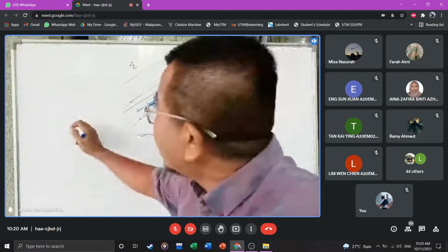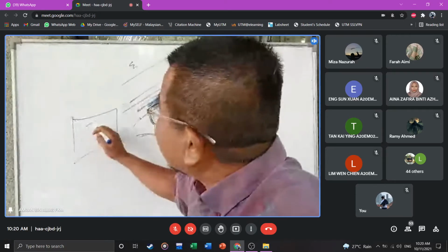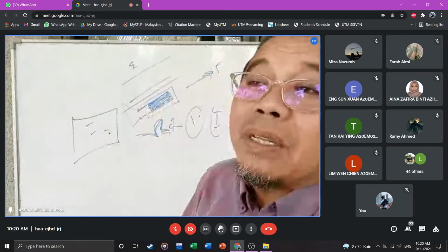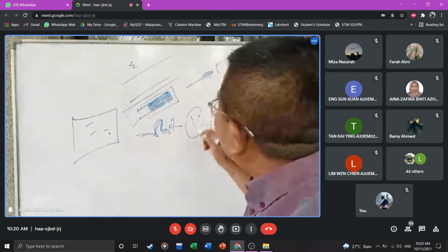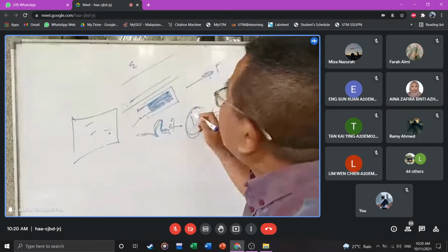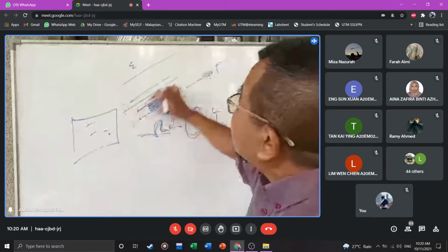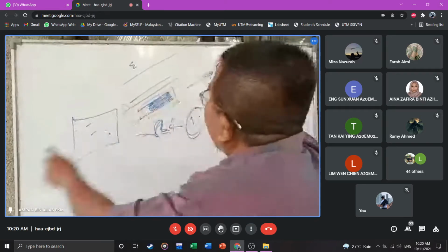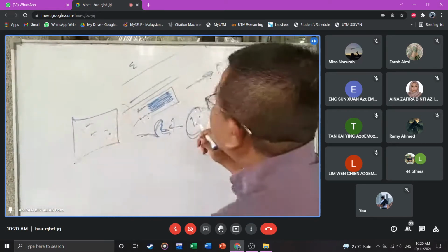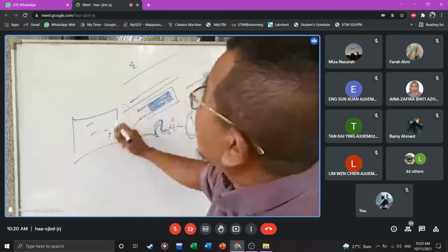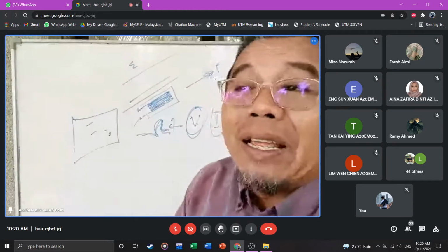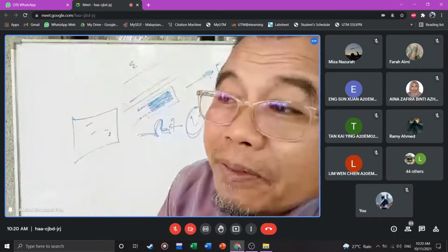That's how the strain gauge meter is working. It's just calibration. If you are reading the voltage, the voltage is changing with the resistance, and then with the elongation. The change in that, we calibrate back with the strain. Are you with me? Yes.